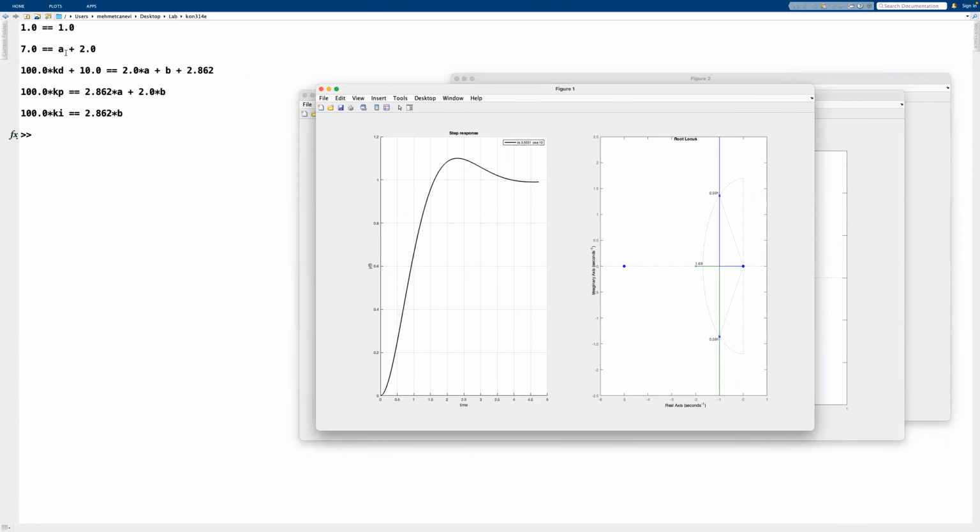Now we can see here, first of all, we have one more set of equations than the previous pole zero cancellation method. We can directly conclude what A is, which is 5. But other than that, we have B and then the 3 controller parameters. So if you look at these 3 equations, we have 4 unknowns. Or if we look at these 4 equations, we have 5 unknowns. So it means that we have one more unknown than we have equations. This brings up the following. If you have this sort of set of equations, it means that you have an infinite amount of solutions.